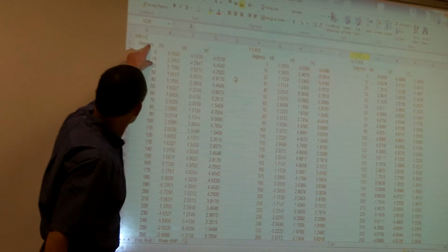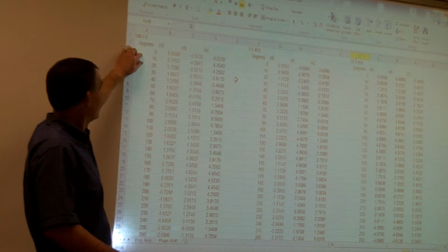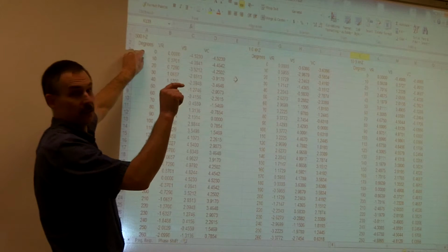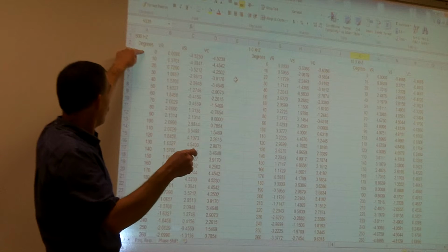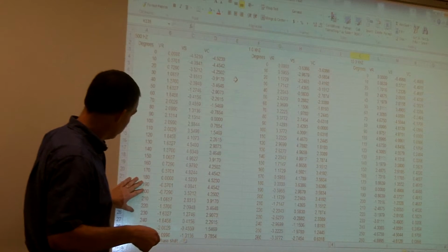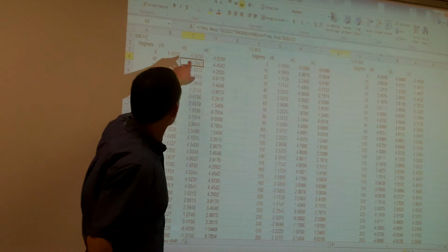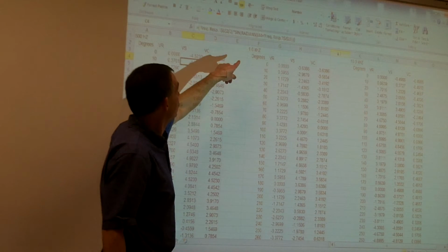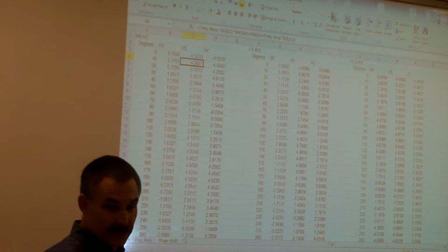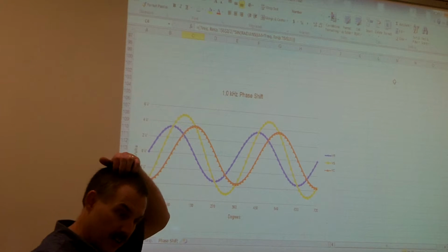So I'm doing that to graph out a sine wave. We know that one complete cycle is 360 degrees, right? So we reference everything. This is where we used our instantaneous formula. We knew the value of that data point by using our instantaneous value: at 0 degrees it would be 0, but at 90 degrees it was going to be at our peak voltage. So we looked at our angle, put that into our instantaneous value formula, which is just our peak voltage times the sine of theta, and it automatically created our graph. We used to do a lot of graphing on the calculator, but this shows us all our frequency response curves.